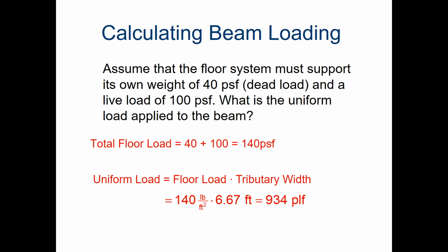All right, so the total floor loading there was the 140 pounds per square foot, and so then we have the floor load times the tributary width is the pounds per linear foot. So PLF is pounds per linear foot.